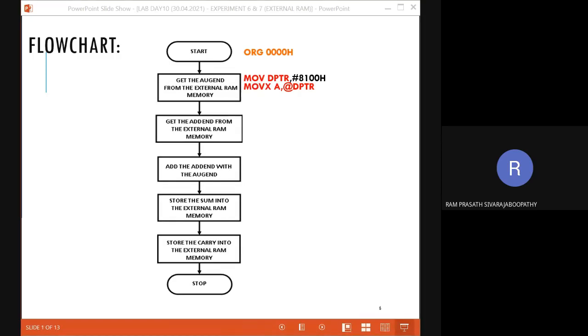Yes. Very good, Danya. MOV B, A. Okay. MOV B, A. That's what I am going to do. Once we have taken the first data, what do we do? From the accumulator we are keeping the data in another register. Here we are preferring the B register. Why I am preferring the B register is that when I am writing a multiplication or division program, obviously one of the data must be present in the B register, correct? So for that purpose I am using the B register. You can also use R0 or R1, whatever register you have, or any memory location. That's your choice. It need not be only the B register. That point you have to understand. Somewhere I have to keep the first data. I have to free the accumulator.